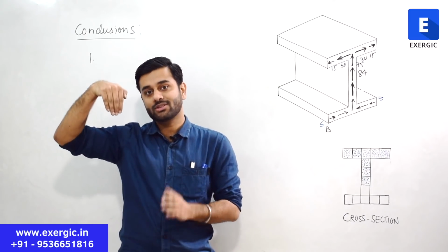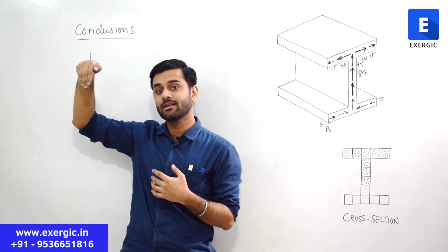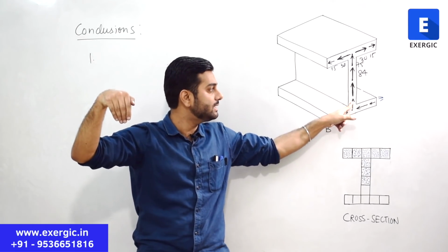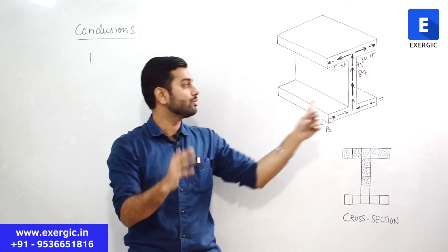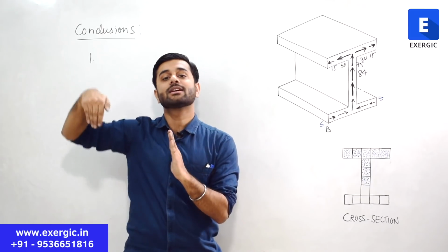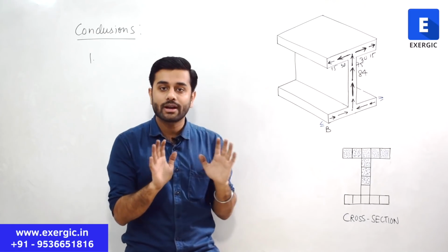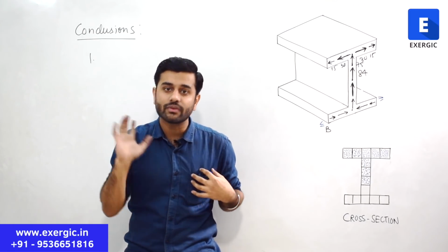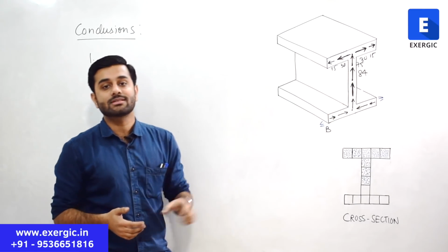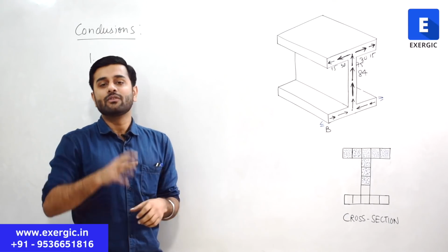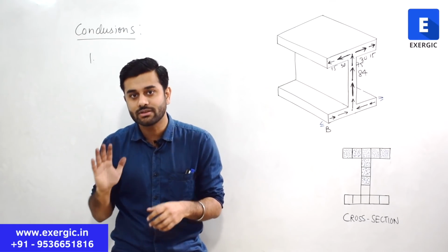That P force is going to get resisted. That same P force that I showed on a cantilever beam, a force P was acting. That P force is going to get resisted by these upward shear stresses. If you take the resultant force due to these, this will be equal to the applied shear force. They will totally balance each other. Clear? Horizontal ones are already balancing. So this is what you can write in the first point, that there is no net horizontal shear force, and the net vertical shear force here will be the same as the applied shear force in the transverse direction.